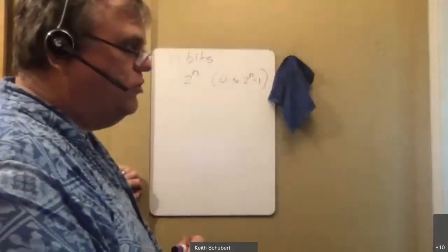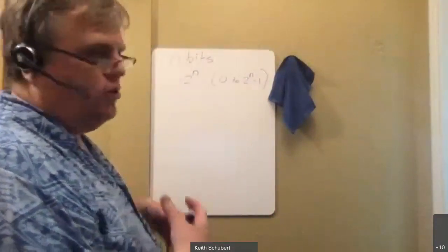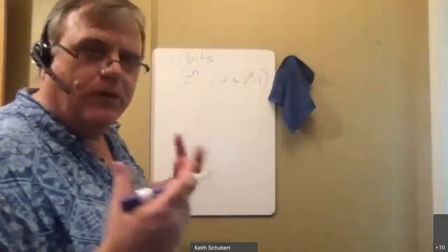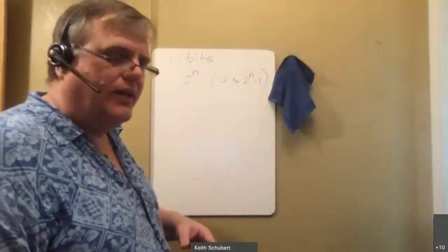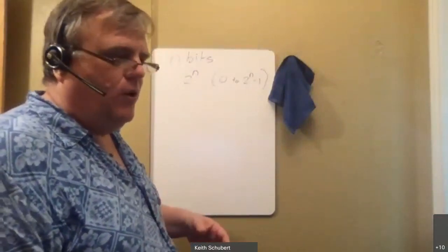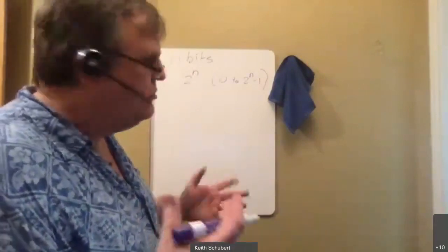So often what we'll do is try to approximate these. And particularly with larger counters, you're pretty much stuck with binary counts. So for instance, you have to do things like you've got a 50 megahertz clock and you maybe want to run something at 75 hertz or 50 hertz or something of that sort.